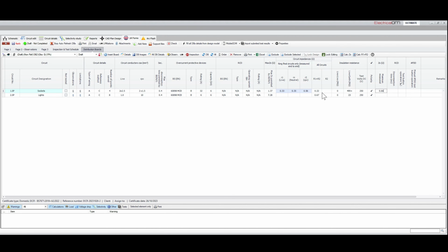And the importance of the ZS at the end is obviously we've been interfering with a lot of these connections. We're taking a live measurement through the actual system during working conditions to a point, although there's no load. So if there's any issues within the MCBs or any of the switchgear leading up to this point of work, if you like, we obviously know there's distribution circuits involved leading up to here. You know, the earth path's intact and measuring out as it should.